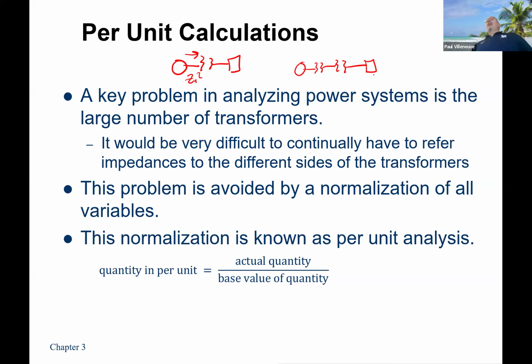And so what we're going to do today is develop the concept of a per unit, which is just another way to say ratio, a fancy way to say ratio, essentially. We're going to do everything in per unit, or as ratios, based on some typical or base quantities. And what we're going to see is if we do repeated calculations on systems, per unit actually makes things much, much easier.